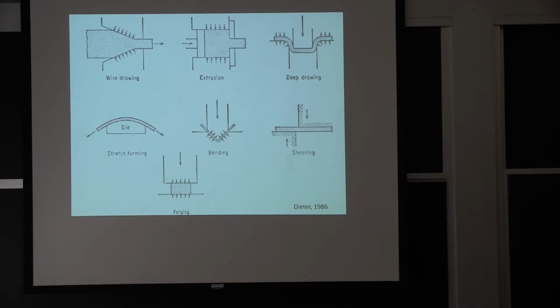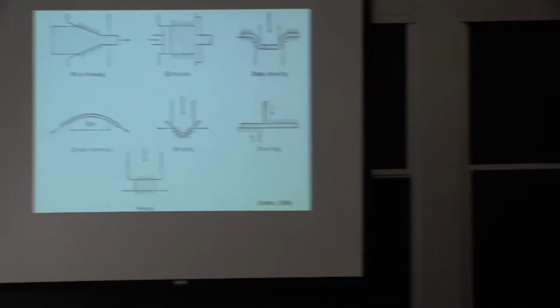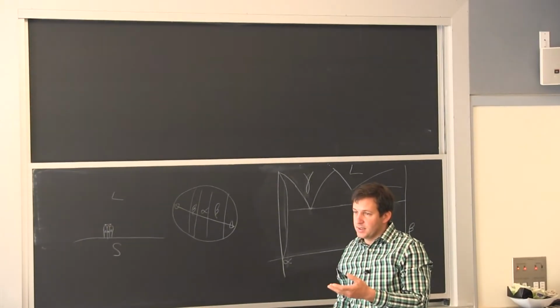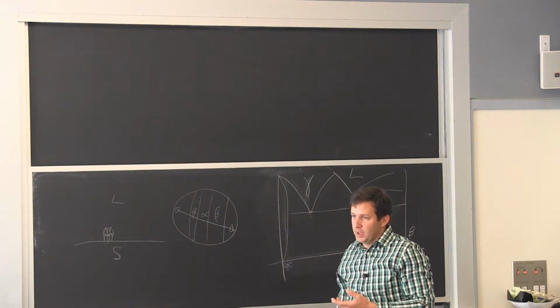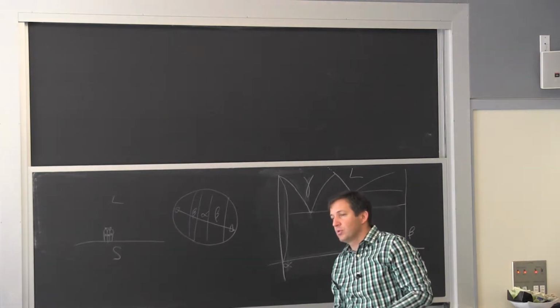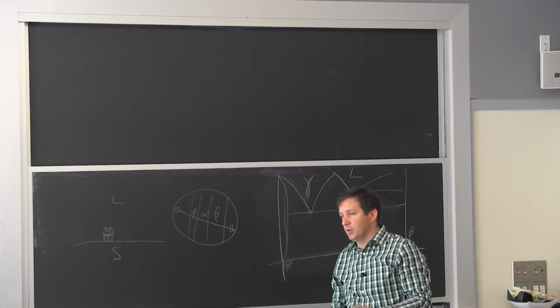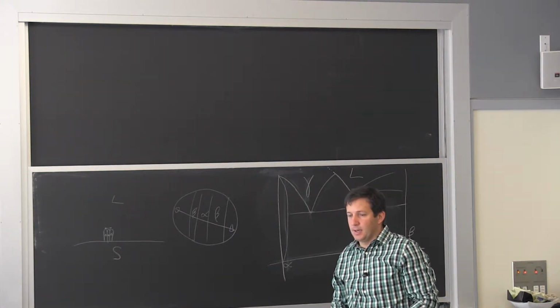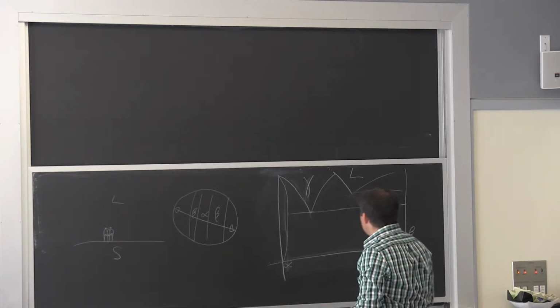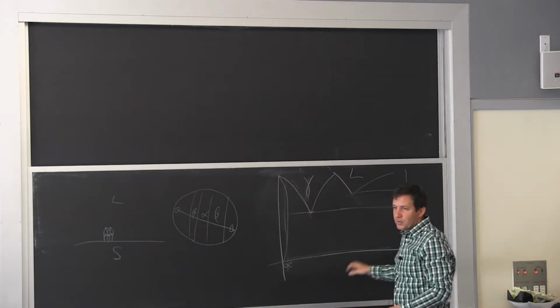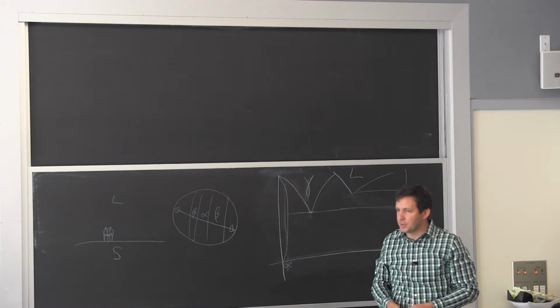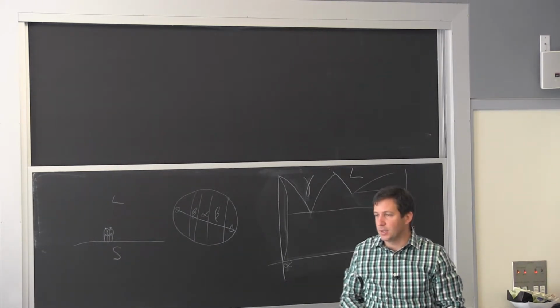When you're a single phase and you heat up, the only thing that will continue to take place is the recrystallization and the grain growth. And that will only reduce your yield strength. So it will only soften it. In steel, it's very different. In carbon steel, because of that transformation, when you go from here and you make all those phases, there's so many things you can do. And we'll start talking about that at the end of today.